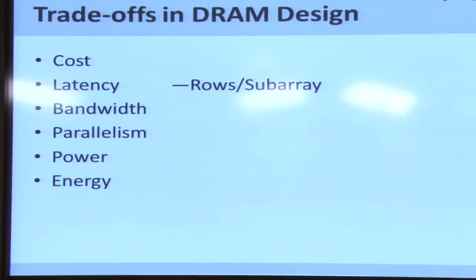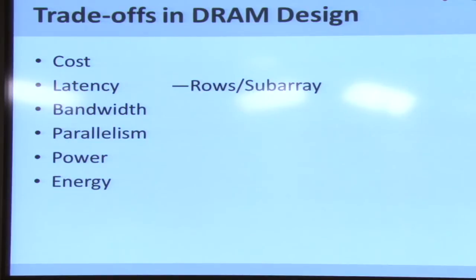Okay, so now because you introduced the terminology, let me talk about it anyway. So this is a DIMM, right? But in this DIMM, there are 8 chips on this side. There are 8 chips on the other side as well, right? So in total, this particular DIMM has 16 chips. This is what is called a dual inline memory module, which means I can either access these 8 chips at a time, or I can access these 8 chips at a time. But I cannot access all 16 of them simultaneously. That's what is called a dual inline memory module.